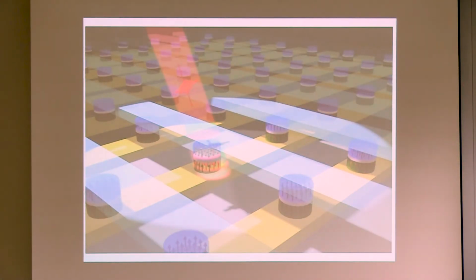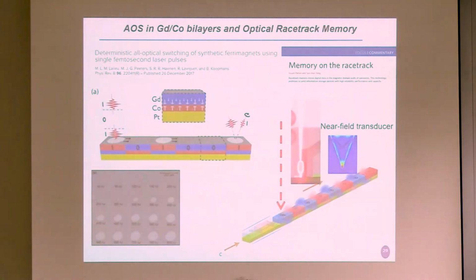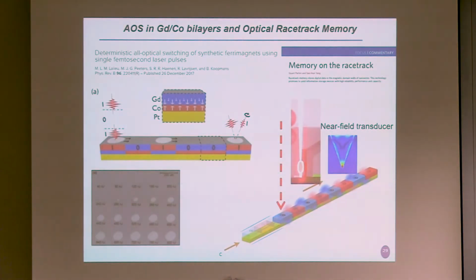Anyway, that's our artistic vision of scaling up this magnetic tunnel junction as a random access array. I see similar pictures. It seems your artist is better than my students, but the idea is the same. Of course, the biggest problem is addressing the size mismatch between a small magnetic tunnel junction and the diffraction-limited laser beam, either coming out of a grating coupler or from free space. It seems the plasmonic near-field transducer is a solution.